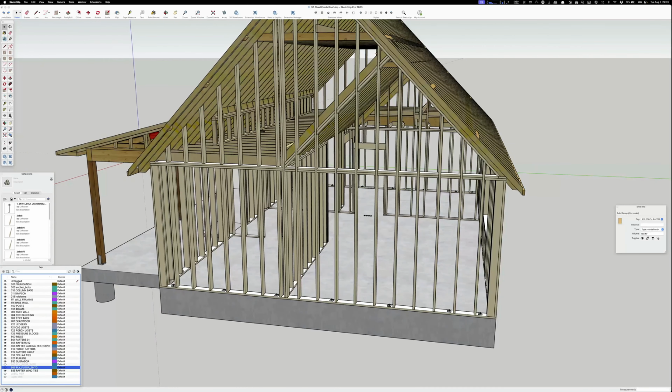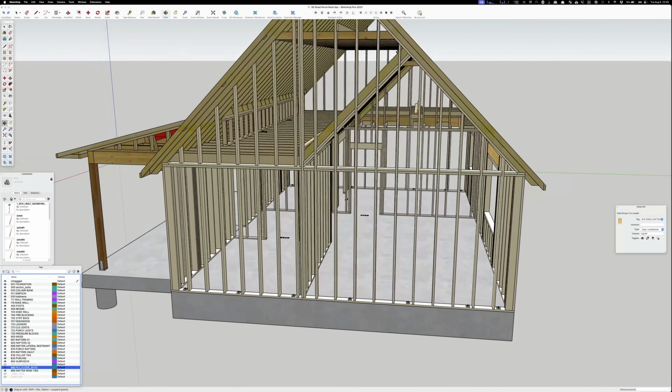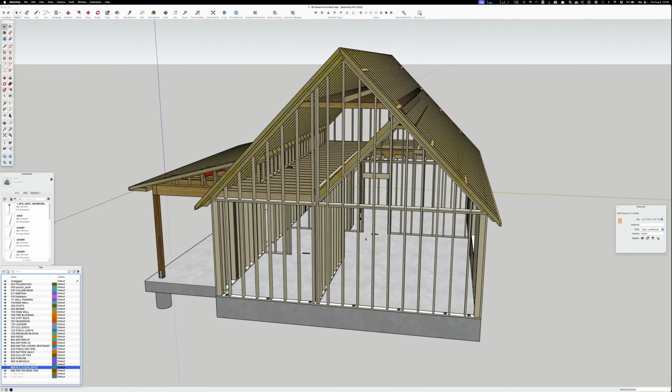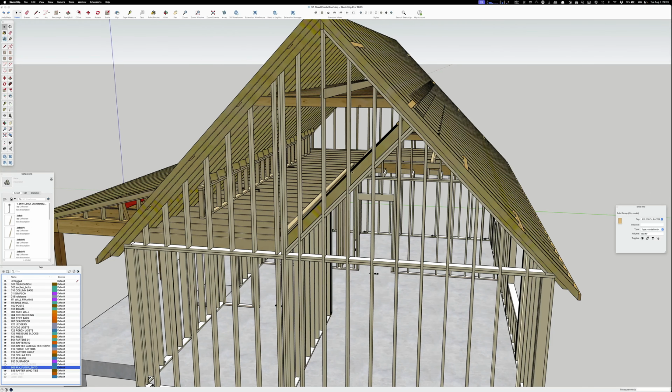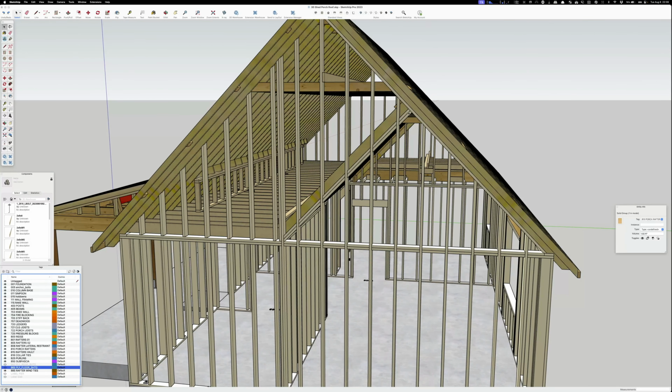Then, while I was wanting to showcase that, I thought, well, maybe we could do a vaulted ceiling. That would be kind of cool. And there's different ways to do the vaulted ceiling. On this end, you're going to want a balloon frame all the way up. And then you're going to put in this fire blocking, but it's also a sheetrock nailer. One of them is flush to the bottom of the rafter, and the other one sticks down so that the sheetrocker has something to nail to.